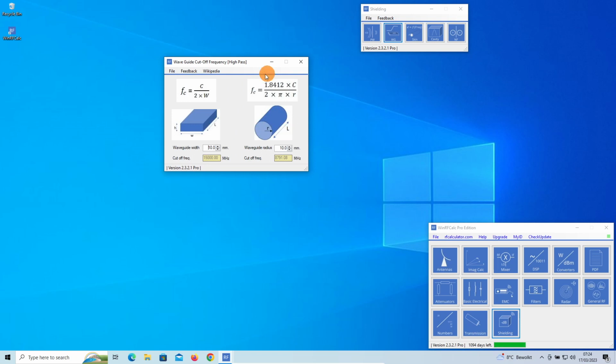Waveguides. Waveguides are often used as solutions to transport something into a shielded room. Could be a fiber or something non-conductive. If you have a rectangular waveguide or a circular waveguide, well, change the dimensions here and it gives you the cutoff frequencies.